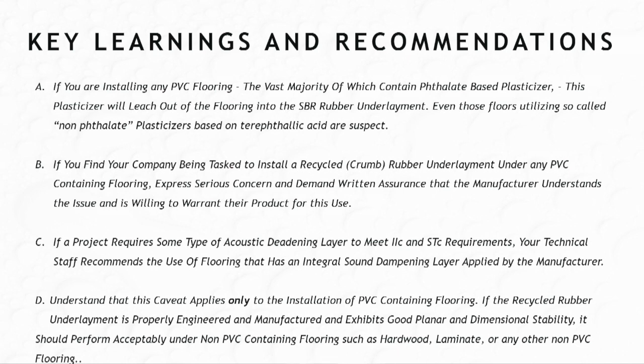PVC plasticizers, these phthalate-based plasticizers, are not covalently bonded to the PVC matrix. They're in there as a mixture. They soften the mix, make it so it's a useful material, but they seek equilibrium with their environment, which is a diffusionary process, and basically they leach out of the backing. This is not something you cause, this is just something that happens.